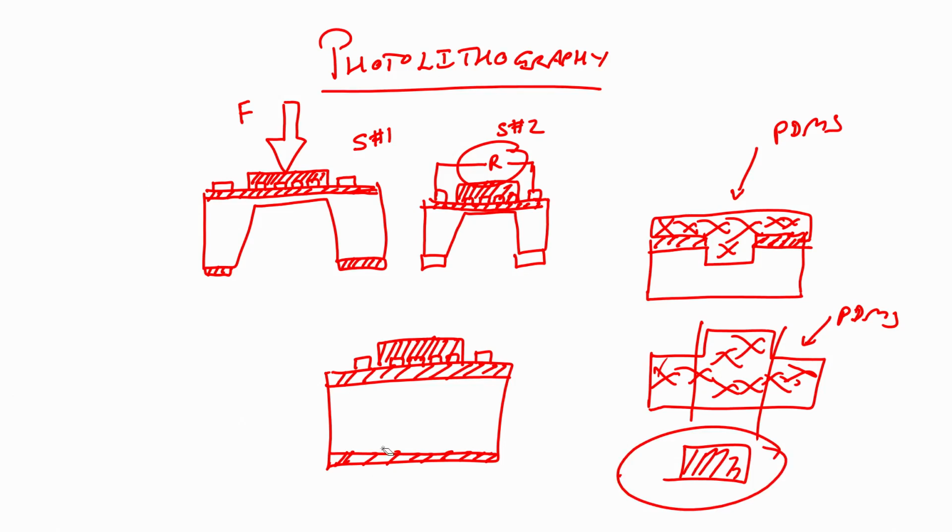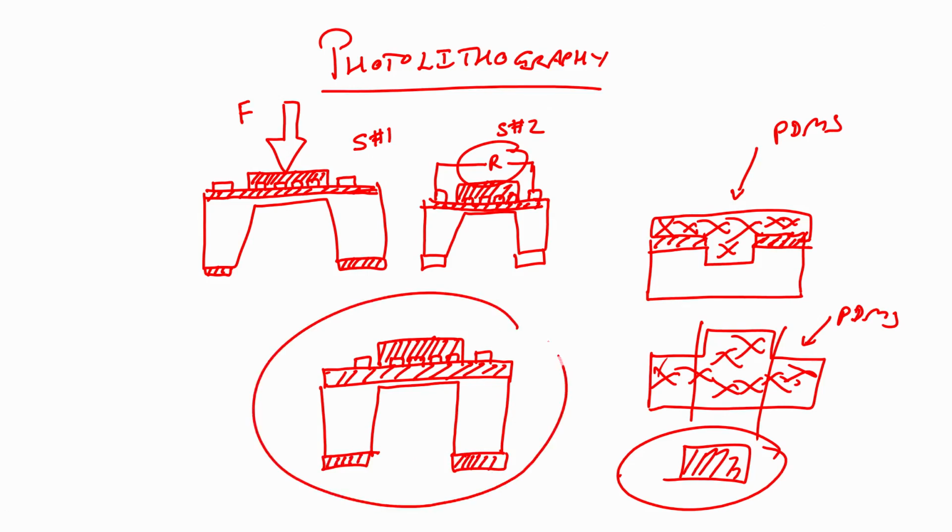I will do the same lithography and I will open a window from the back side. What does that mean? Let me just show it to you. I will remove silicon dioxide from the back side and then I will do DRIE, right. When I perform DRIE, what will happen? My silicon will get etched to give me the piezoresistive sensor. Now, if I apply force, then this diaphragm will bend, and depending on the force, there will be a change in the resistance in the piezoresistive sensor.